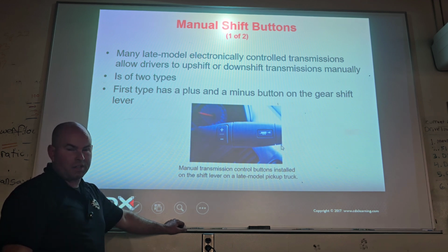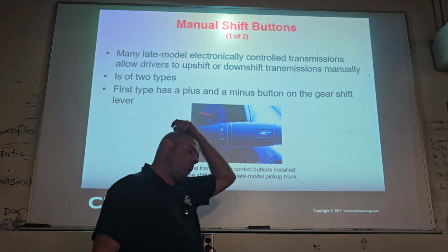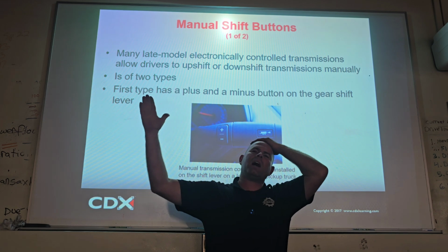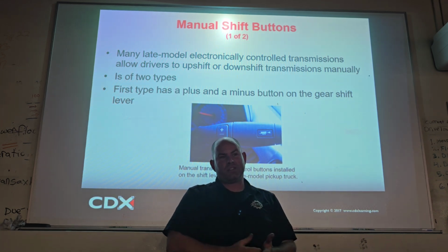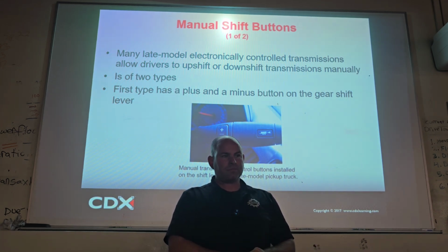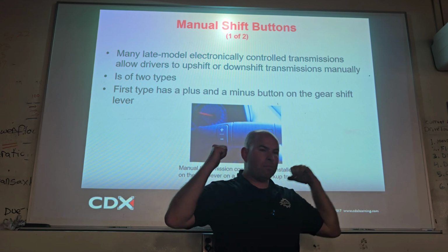I don't think I put that on here. Tow haul mode a lot of times will delay your shift points higher, increase your line pressure. Why do you want that? Towing a big heavy trailer.